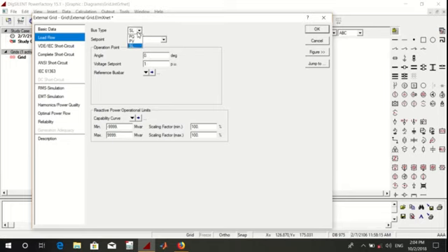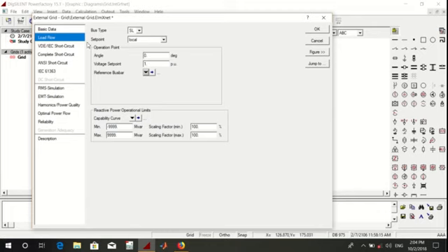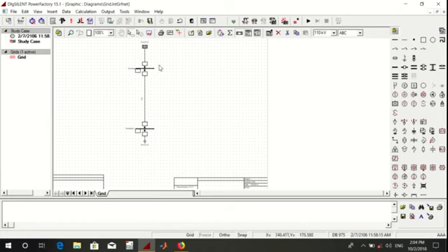Here the voltage is 1 per unit. When I select the type of the bus, immediately the parameters become automatically like this. In slack bus it becomes voltage 1 per unit and an angle of 0 degree. If I select PV, there are other parameters that we need to define. And if PQ, other parameters are required to be defined by us. Then I select slack bus. Go here, we do not define anything. Then all has been done regarding our source or the grid feeder.